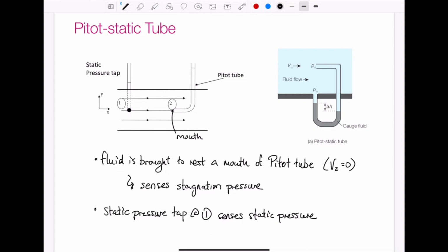This is typically found in pipe systems, and that's measuring the static pressure at that wall. If we extend the pressure down to the streamline that is going to that pitot tube, then we can calculate the static pressure along that streamline. So this would be more common for liquid flow.